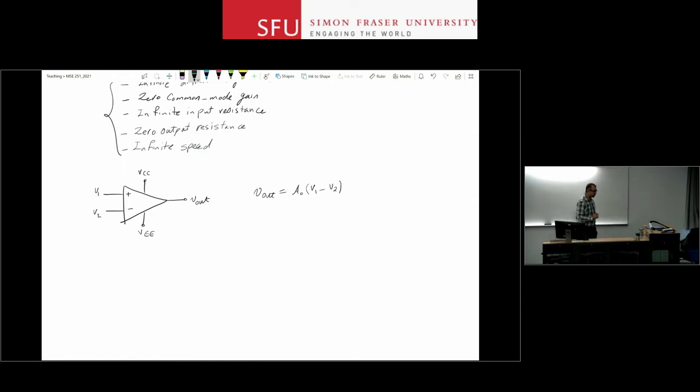For an ideal op-amp, there is an interesting case. So I know V out is bound by VCC and VEE, right? So again, going back to our transistor amplifiers, you know that when you have just resistors and capacitors in a transistor amplifier circuit, and let's say the devices are in their active regions, none of the voltages anywhere in those nodes in your circuit may go above your power supply, either at the top end or at the bottom end, right?